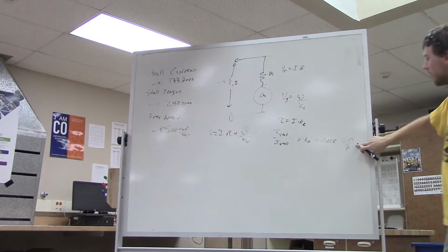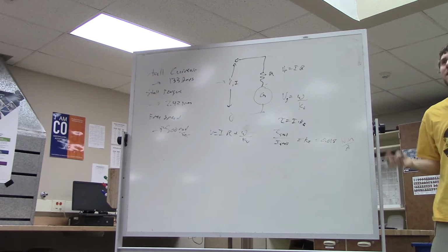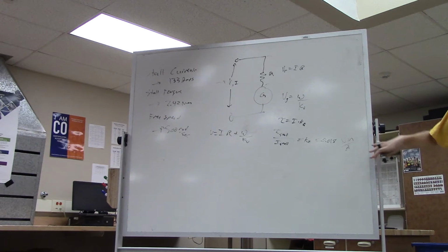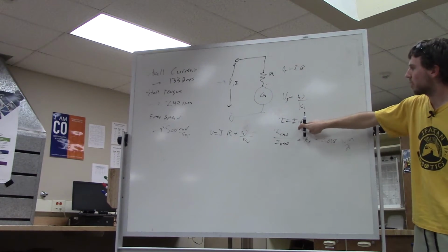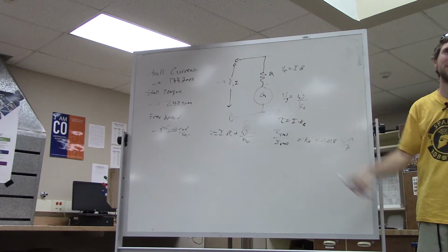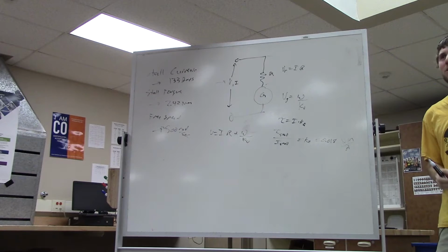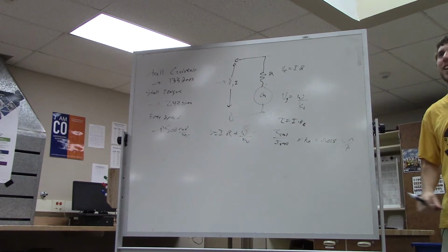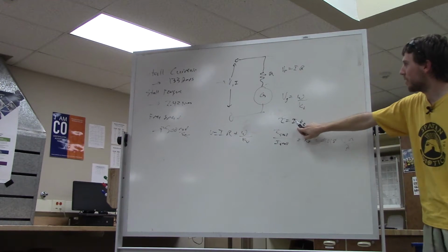Well, this is not arbitrary, right? This says to convert from amps to Newton meters, you multiply by that, which is exactly what we're doing with it. So the units actually make a lot of sense. I've seen this equation written out as times KT and divided by KT, so just be careful which convention somebody picked. It's just a constant, doesn't really matter, but you want to be consistent through all your equations. I picked what I believe is the standard, but I could have inverted it, just fair warning. So now we know KT.